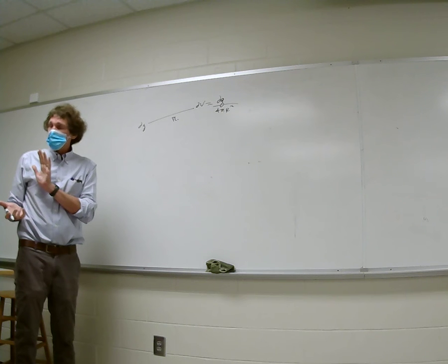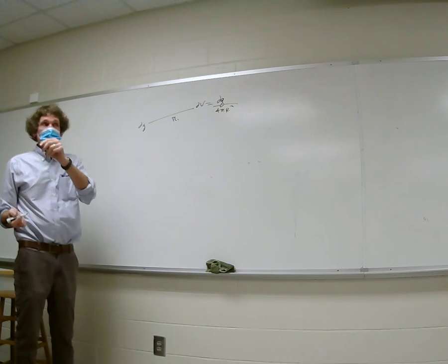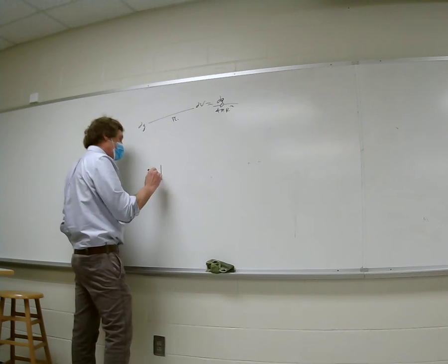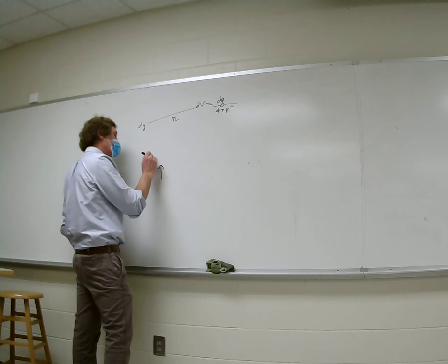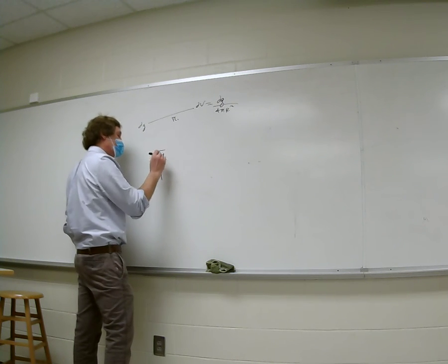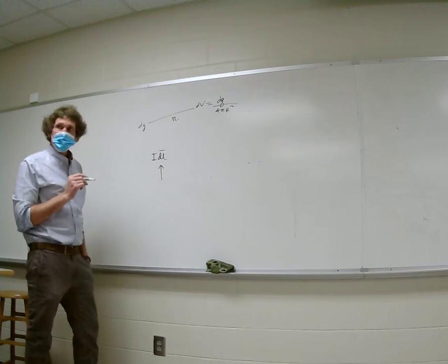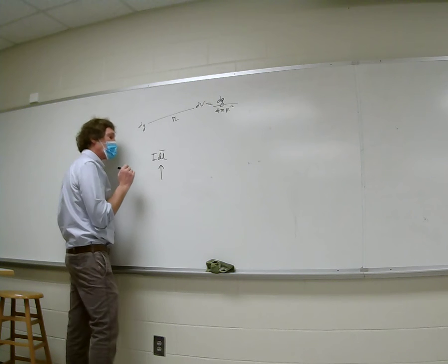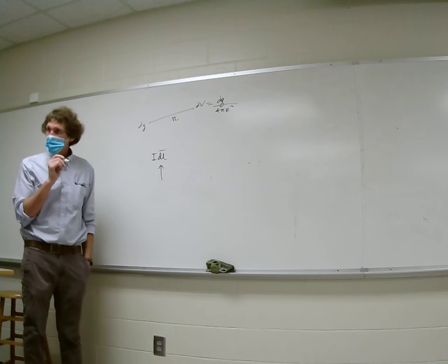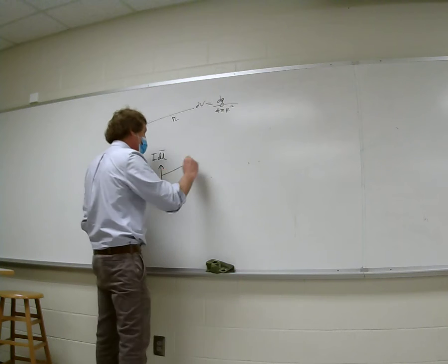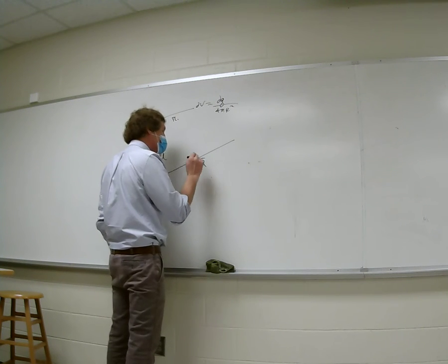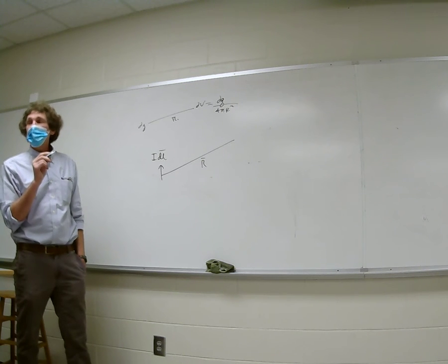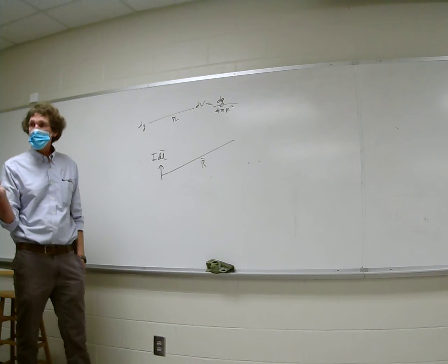Well, here's how we do it using potentials with current to get the E field. Now you can write this down. We have a little chunk of current, I dl. Now the dl is actually the vector sense of that chunk of current. I is just the magnitude. In the book you'll have I naught, but I'm going to leave it as I in general, okay? Now if you go from the center of this thing, a distance r away, you're going to get something called a magnetic vector potential A. You don't need to replicate this work. This is to give you perspective.